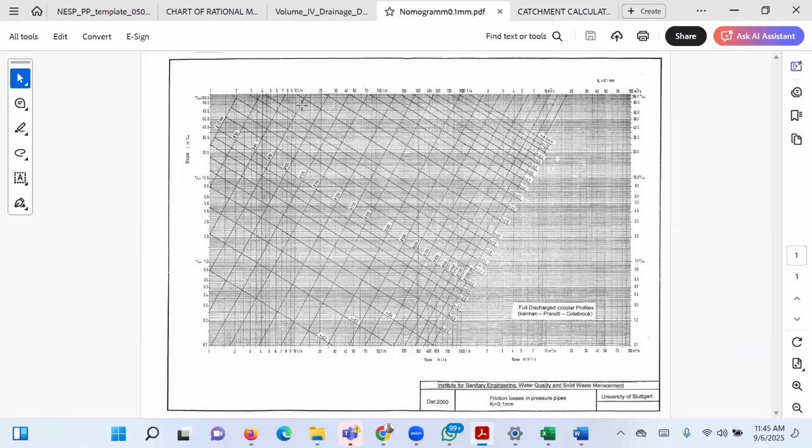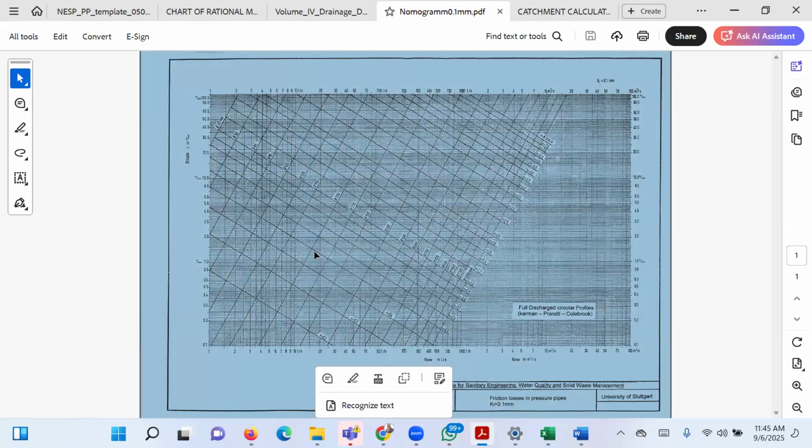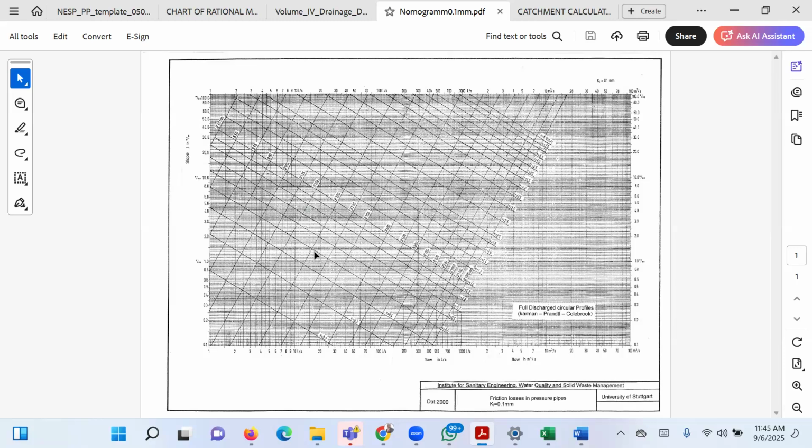Then the second thing is, I don't know if it's a rule of thumb or an appropriate thing to do. When there's a road design, the slope is just referenced from the road when they are doing the pipes. That's the perfect way to do it. They cut and fill. Yes, that's the best way to take the slope.